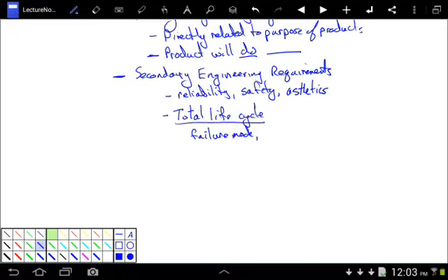And you can see that and get off your bike, and it's okay. You don't have a bike anymore, but you still have your face, right? One of the problems with a carbon frame bike is that when they fail, they shatter, right? They fracture. They completely break. So the front end of your bike will completely break off, and you'll go tumbling face first into the pavement. So how is your product going to fail, right?